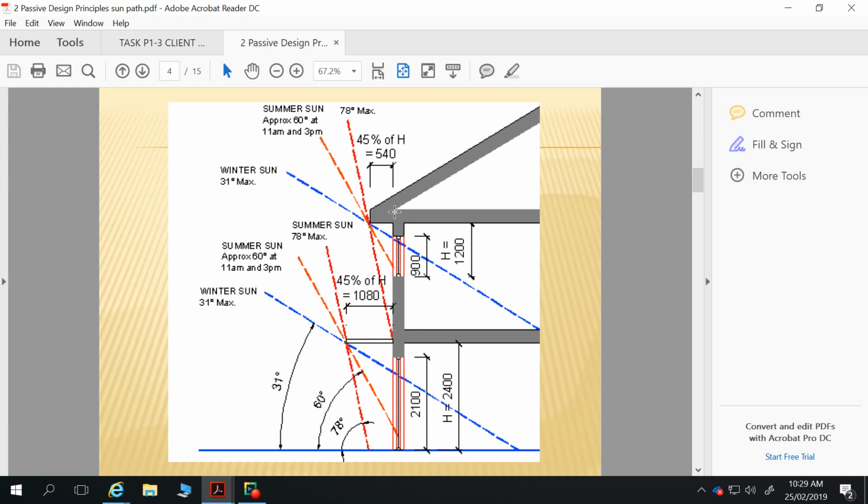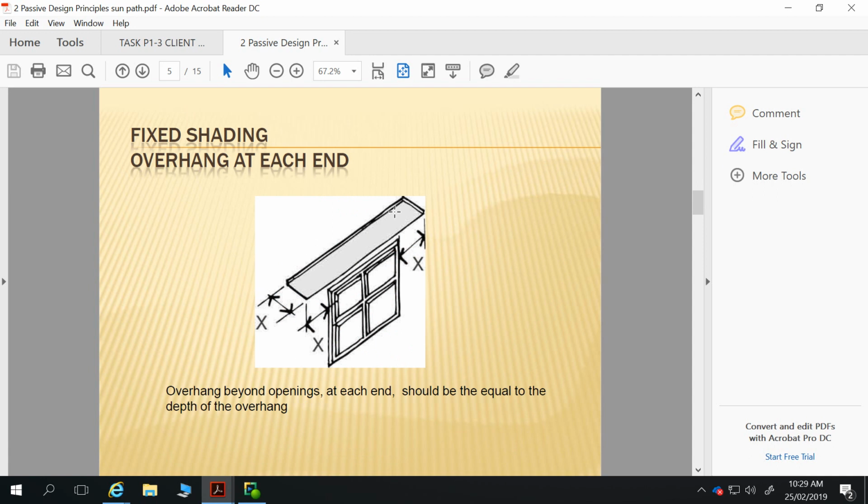And that's that same diagram, a bit expanded for two-story construction. For that, you include a shading device over your lower windows to enable efficient solar access to the building in the upper story, and then efficient solar access to the building in the lower story. So that's basically just built-in shading for the north.